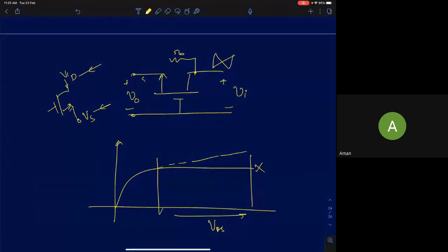In digital circuits, it is interchangeable. In analog circuits, if and only if you are using a MOS device in linear region, where you are going to use it as some kind of a switch, it is interchangeable. But in an amplifier, it is very precisely defined. Drain will be at a higher potential than the source. So this is drain, and you will still have some feeble current because of R naught, and at a later stage we will calculate what that gain will be as well.